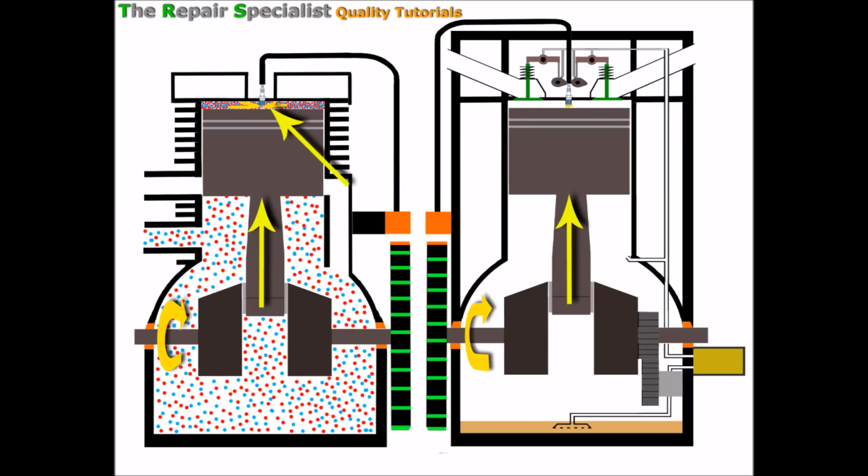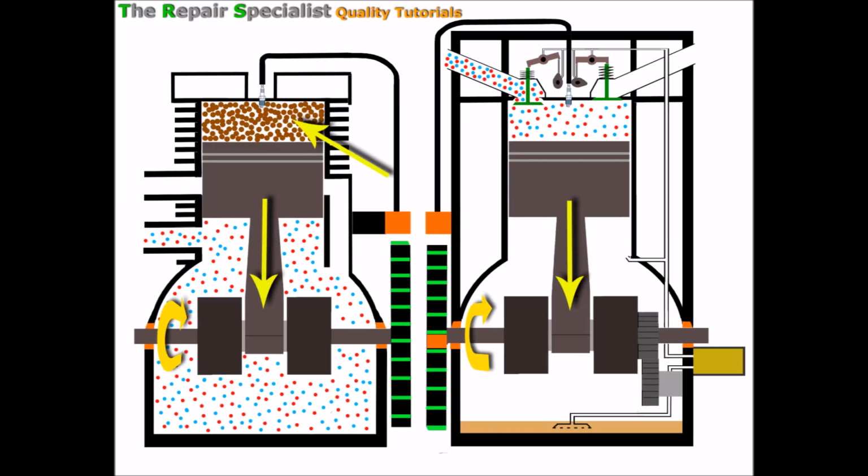But over on the two-stroke here, we're on a power stroke, so that spark is now igniting that air and fuel. And of course that ignition spreads rapidly into a mini controlled explosion. And as we know, this forces the piston downwards with great pressure, and left in the wake there from the explosion is all those exhaust gases again. And at this point we'll just take a little snapshot of what's going on with both engines. We'll see the differences here.